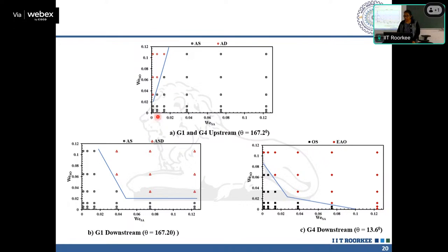Only a change in the area gives you the same type of flow regime, with some change in shape or formation of additional drops. When you combine it with a change in contact angle also, you end up with an almost new flow regime map, with the dominating flow regime being some other type. Encapsulation we haven't seen till now. So this is the result of a sudden change in wettability.